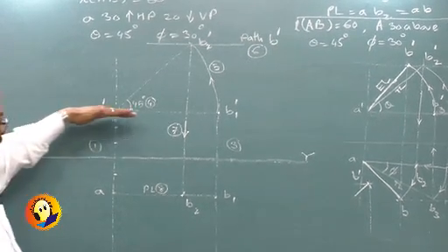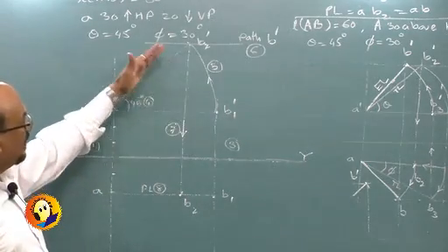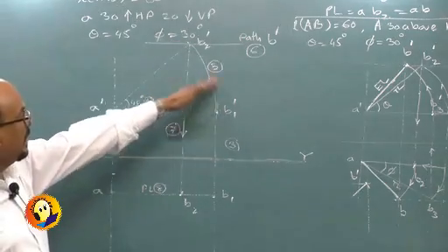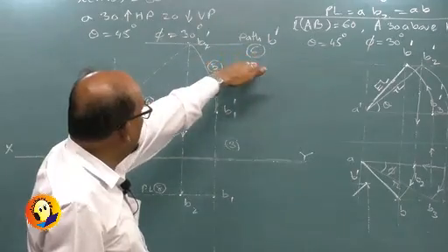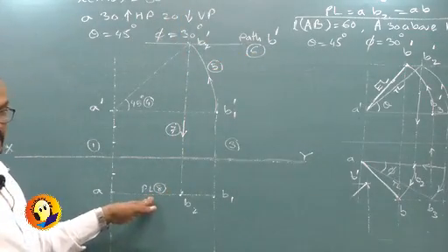So I started initially with line parallel to XY. I have rotated it by 45 degrees. First mark the angle, then I have cut the arc, that is 5. I have got path of B dash, step 6. Step 7, I came down, I got plan length.